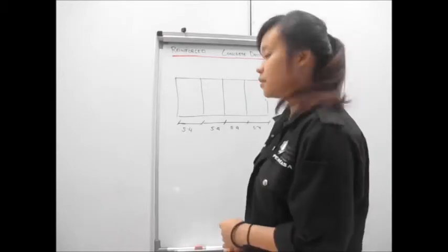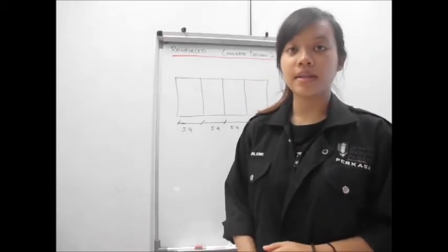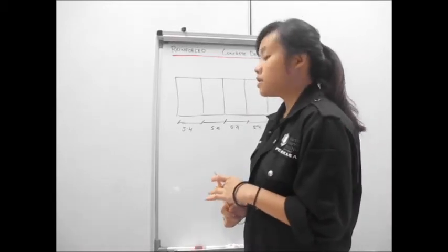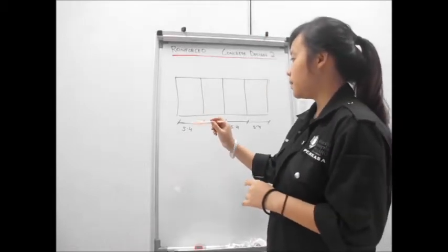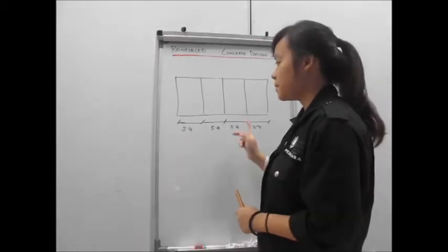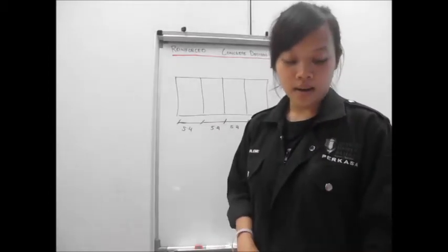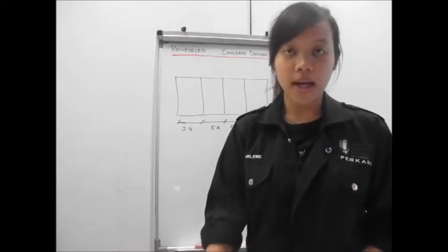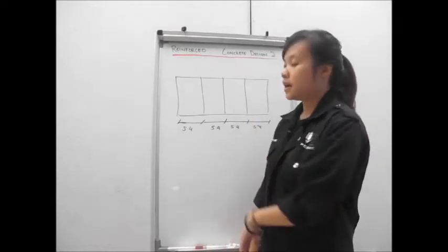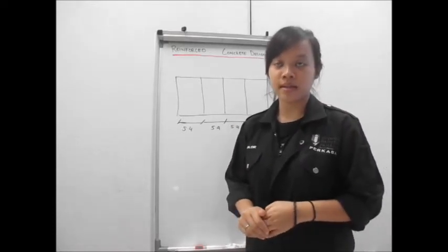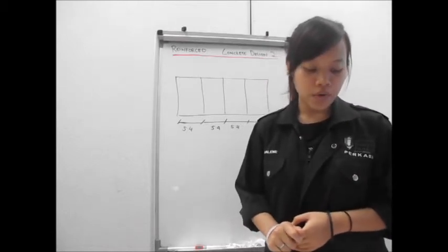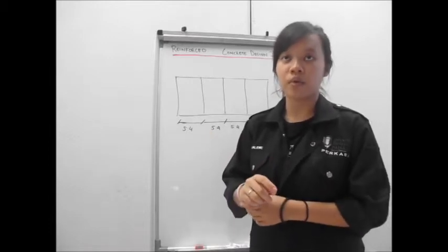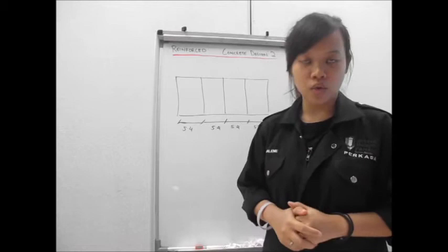Now we would like to proceed with our slab design. For our slab design, we have two types of slab, which are continuous and simply supported slab. For the continuous slab, we chose the slab that has a span of 5.4 meter, and it is a two-way slab. Then to do the analysis of the slab, we need to find the slab thickness, where Lx over d is in the range from 20 to 30. So we decided to use the maximum, which is 30.